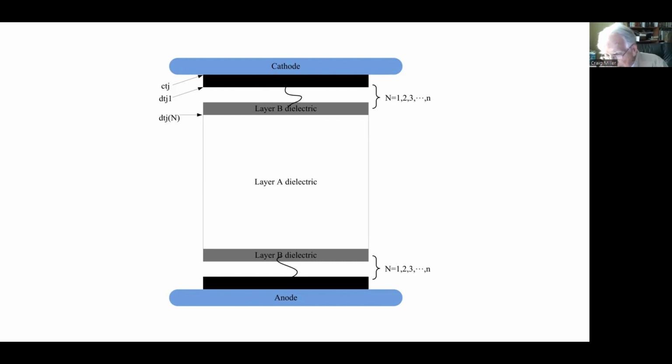Okay, now the reason the relative permittivity is so important, I'll show with a sketch here. This is the sketch for a particular device. This is with ceramic. Here's the cathode, the ceramic, which is alumina ceramic with a relative permittivity of 10, and a vacuum. If there's a perfect joint at the cathode triple junction, the equipotential lines are, you can see, uniform, and therefore the electric field is constant all the way along the insulator.